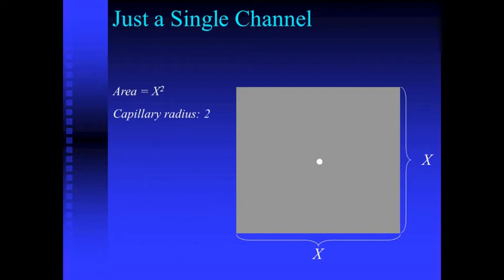If we now also consider a single capillary but with a radius that doubles the previous value, as the porosity grows with the square of the radius, we go from 0.1% to 0.4% porosity for the same block. At the same time, as the flow rate increases with the fourth power of the radius, the calculated permeability for this new block is 16 times greater than that of the block with a single capillary of unitary radius. Consequently, the new block has 1.6 millidarcies permeability.